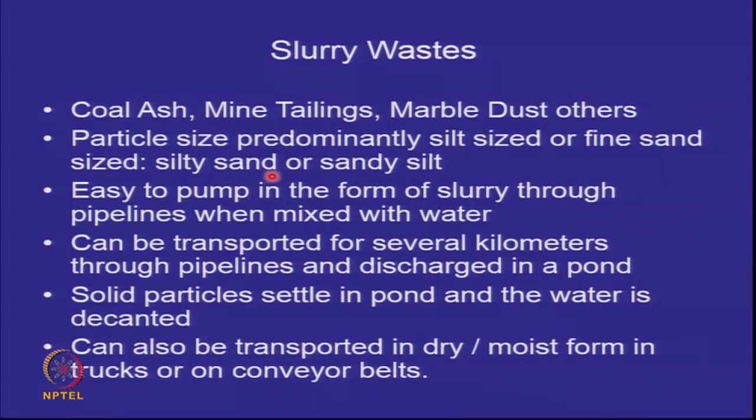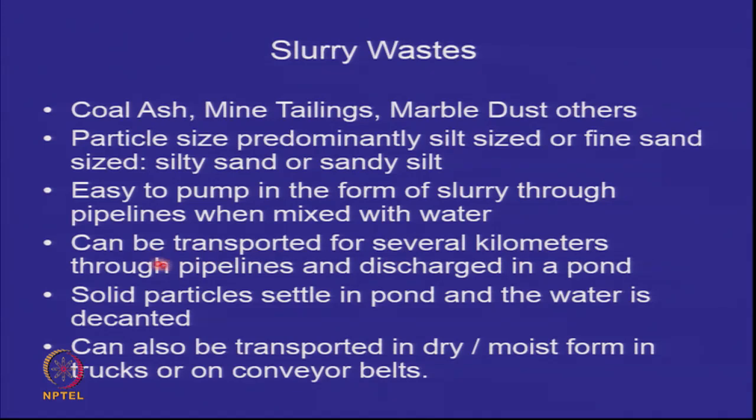So it is easy to pump the silty sand or sandy silt, and especially if the sand component is fine sand. So we pump it in the form of slurry through pipelines, can be transported to several kilometers. So you may need intermediate pumping stations to boost up your velocities, but you can transport the slurry for several kilometers through the pipelines and then discharge into a pond. In the pond, the solid particles settle down and the top water is decanted.